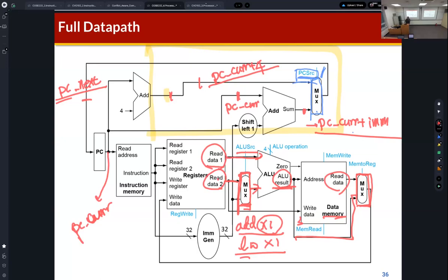If we perform a load word instruction, the destination register is updated by data from the data memory. So there are two different cases, and in this case we need to use a multiplexer, controlled by this selection signal, because we can update the destination register using the ALU result or the data from data memory.